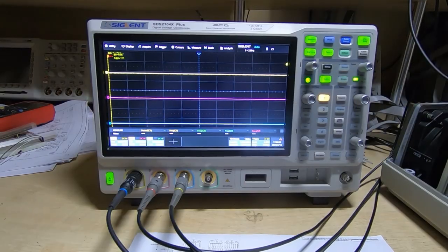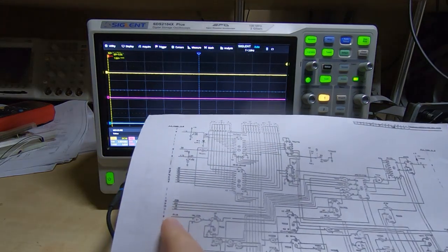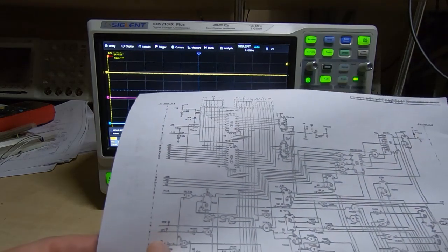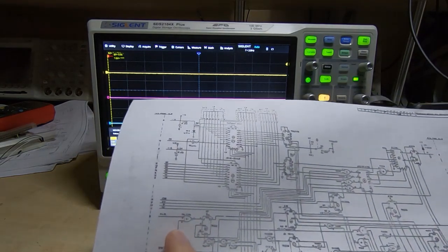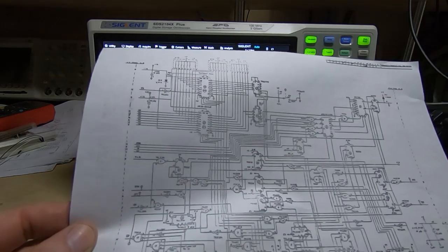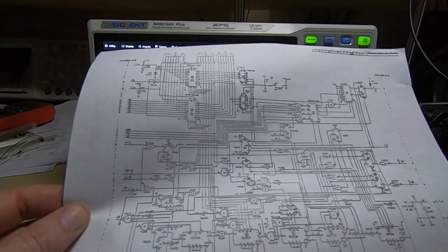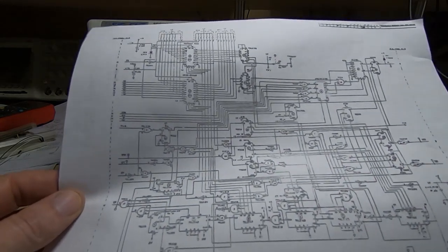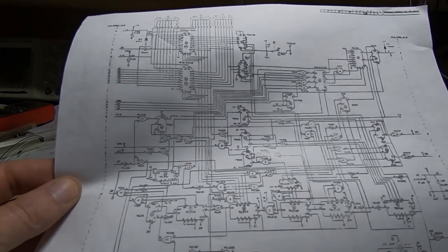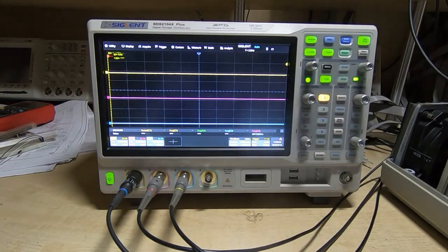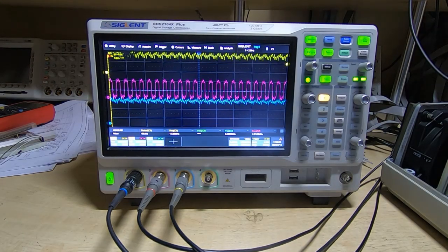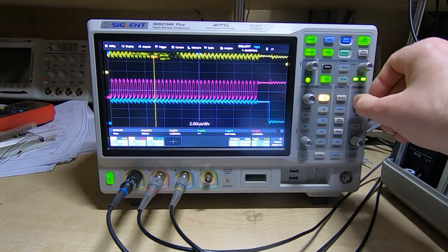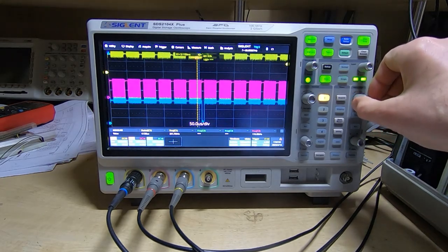So I've got the scope hooked up to those 3 test points, and what we're looking for here are the properly timed signals indicating that the system counters, the video system counters, are running as they should do. As I said, I'm pretty sure they are, otherwise we wouldn't be seeing the display as we are, but we'll just test this anyway. So I'll get this powered up, and sure enough we are seeing exactly what we should.